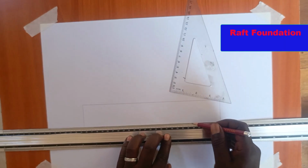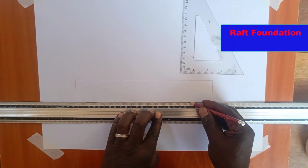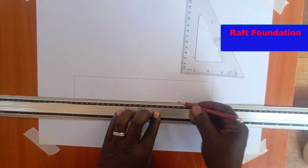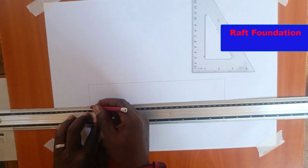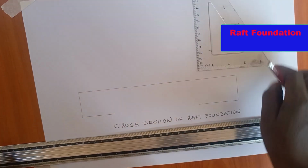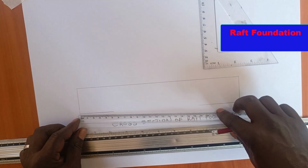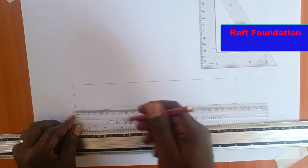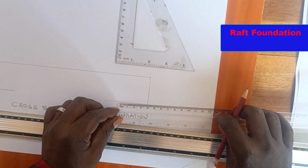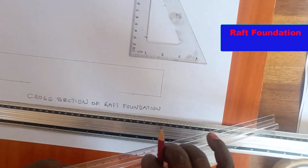So I can draw this line here, which is supposed to be also at 400 millimeter. Then this side also is 400 millimeter. I'll measure it. I'm just making a line. So I measure here 400 millimeter. I mark. Then I measure here also 400 millimeter. I mark. So now I have to use my 45-degree set square.